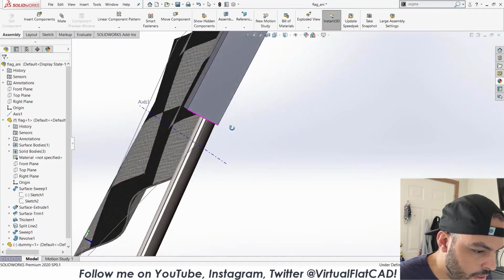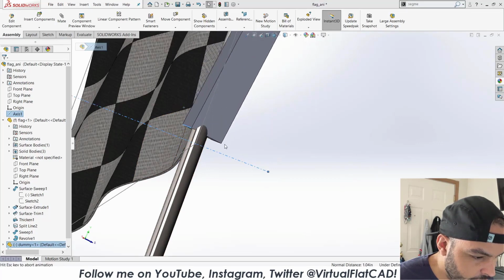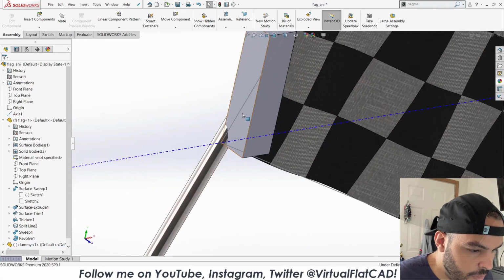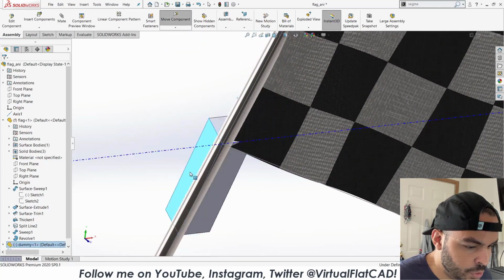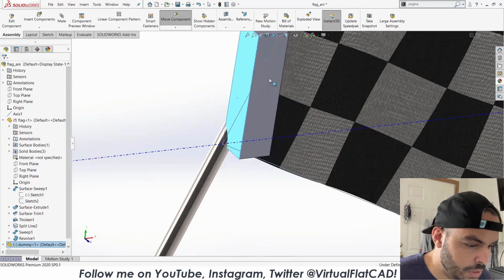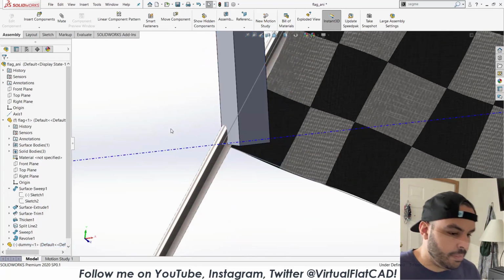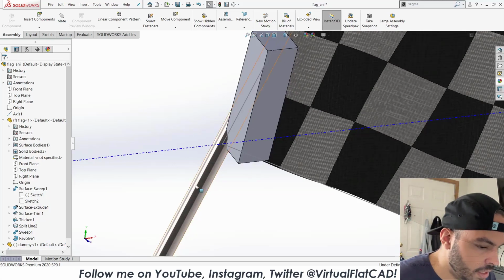Axis shows up, and we can grab that edge and make that coincident. So with me mating the face and that edge to the axis, we should just have a part whose only degree of freedom is to spin around, basically. And that's exactly what we need.